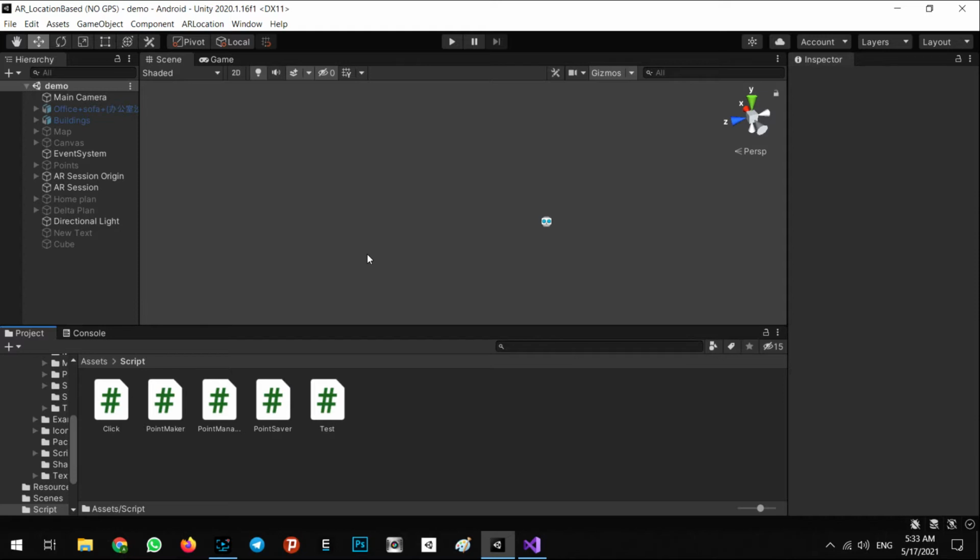The solution is to go to the place where we want to show the 3D model or action, save the positions, and then import the position, rotation, and scale of those points as txt files into the Unity editor, then import them into the project.